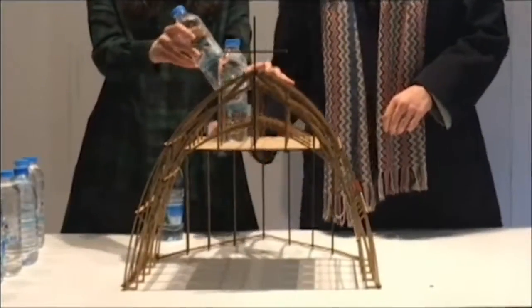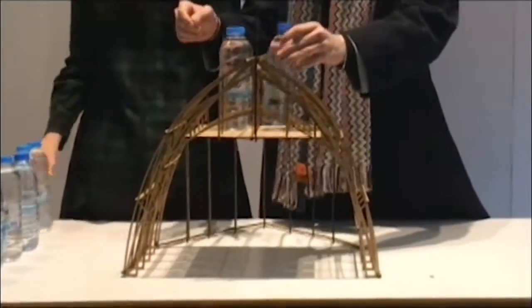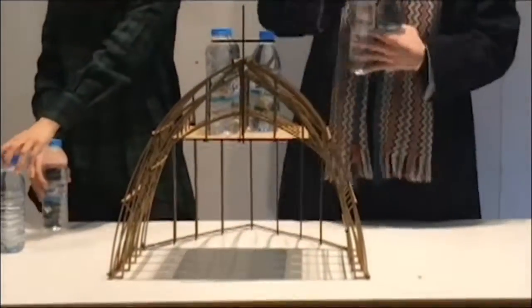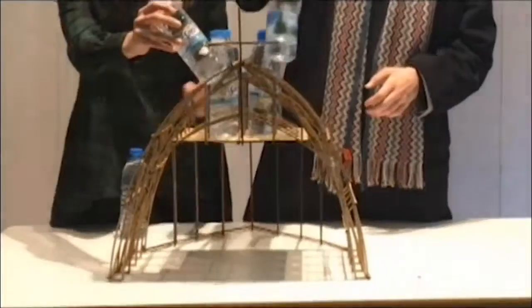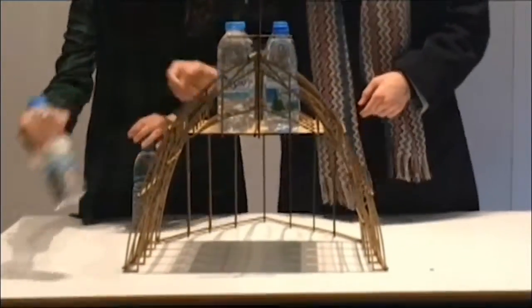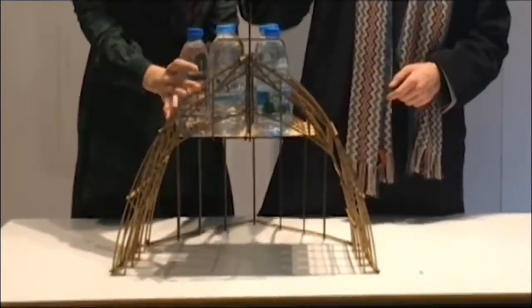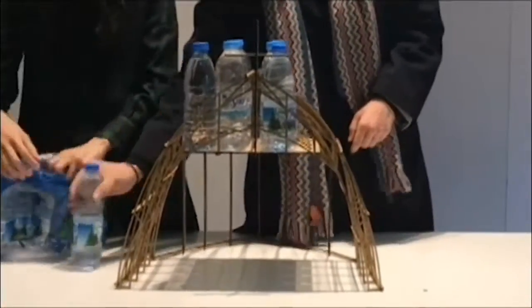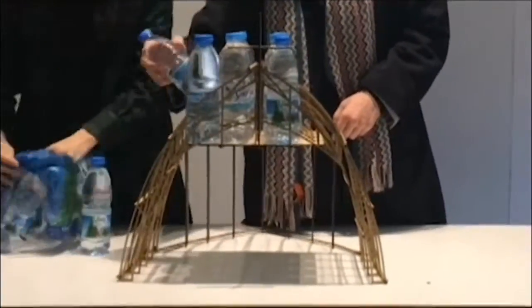As our structure had to be a funicular, the form had to follow the force, so we began to look into arch systems in churches, predominantly the way they behaved in compression. We looked at the buttress systems outside the church and began to make models employing both arches and vaults which would spread the load and remain stable while in compression.